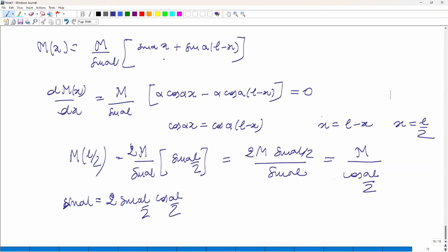But one major outcome is that if we have a compressive axial force, the compressive axial force will amplify the effects of the other actions. Amplify in the worsening sense, because if you have a higher bending moment, it means that you are engaging more your structural element.